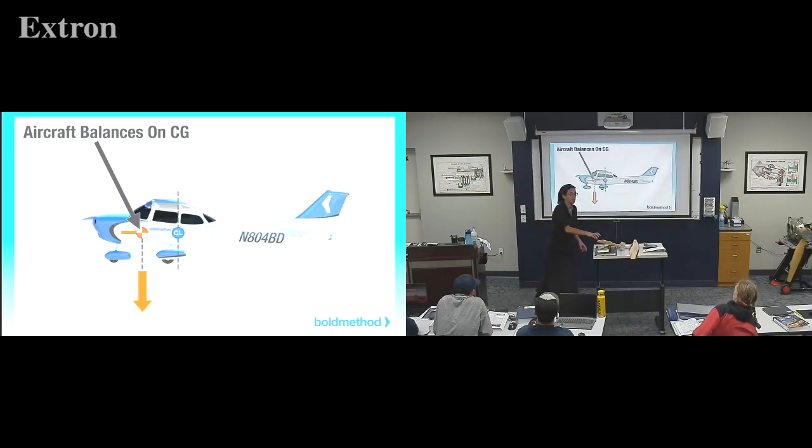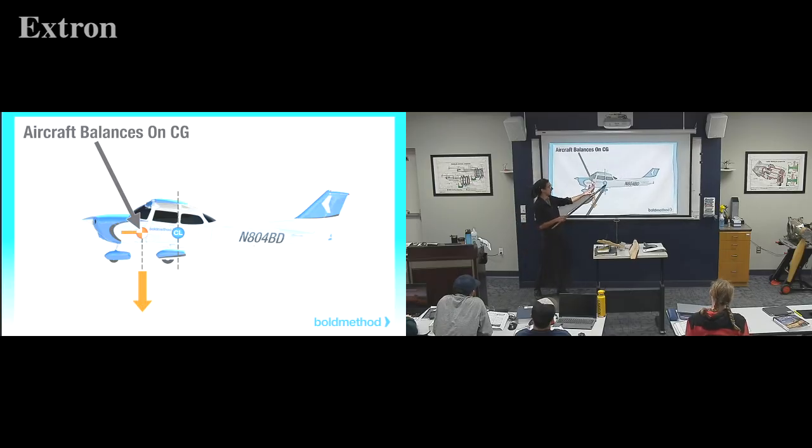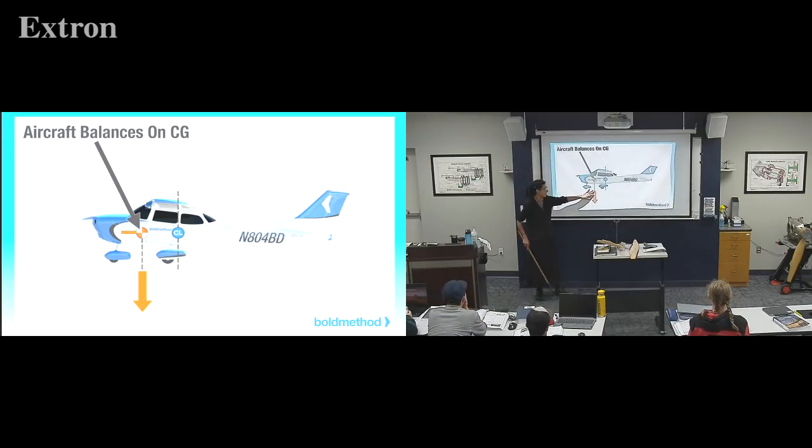But in design and where you place weight, you need your center of gravity, or where all the weight is concentrated, where gravity is pulling down. You need that forward of the center of lift, which is where all the lift forces are considered theoretically concentrated, and we're pulling up on the airplane. Why do you think that is? What other aspect is happening back here, do you think?